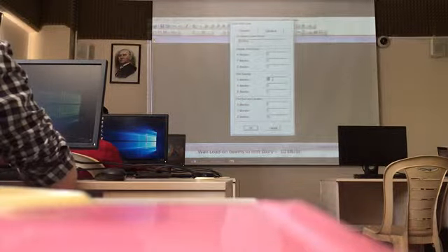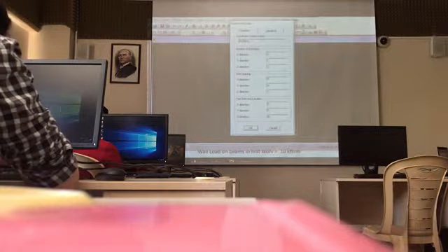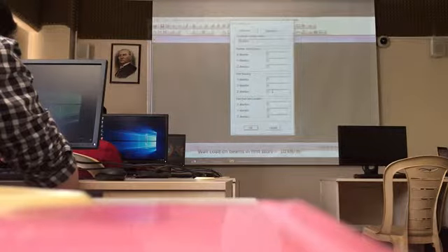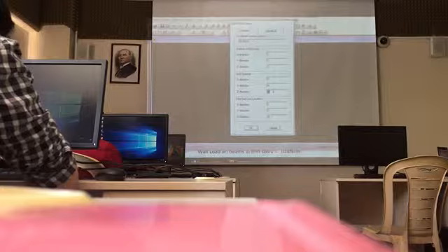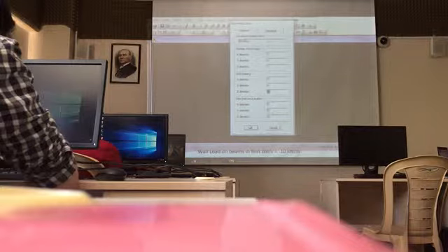In X direction span length is 5 meters. In Y direction 4 meters. Right? And in Z direction we have 3 meters, 3 and 3.5 actually. We can replicate this one also. We can use the replicate command.